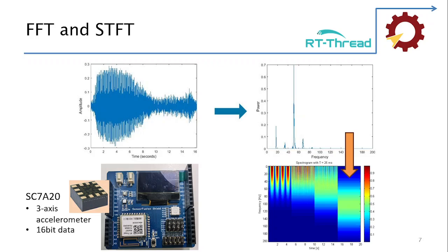For today, I would like to use a sensor based on the hardware that I have here, which is an accelerometer. I will use just one axis of this accelerometer, and I will show you what it looks like in the time domain and in the frequency domain. By the way, I will not do the coding in C directly. I just make use of MATLAB and let MATLAB Coder do the job for the remaining part.